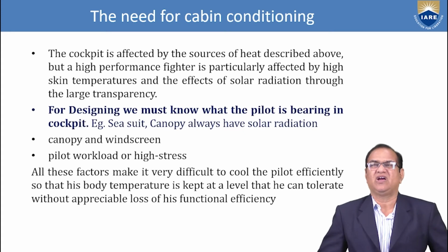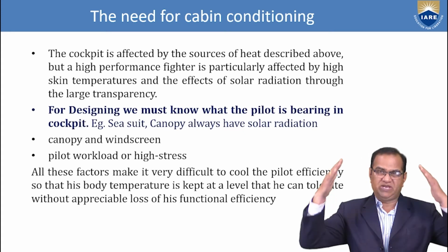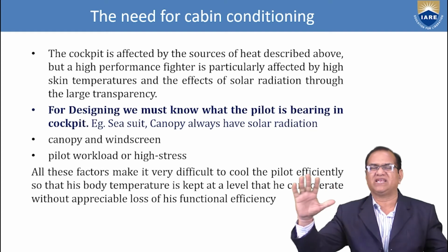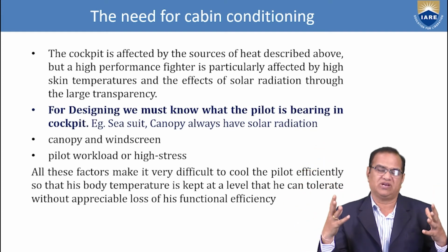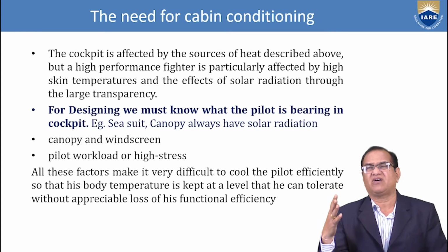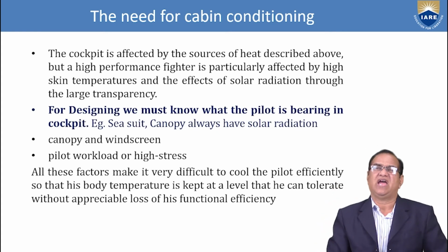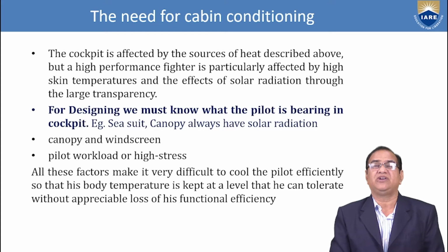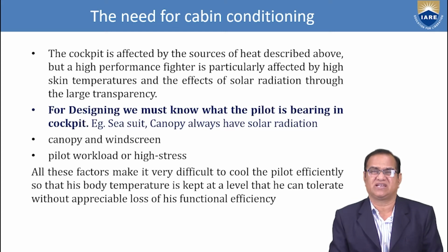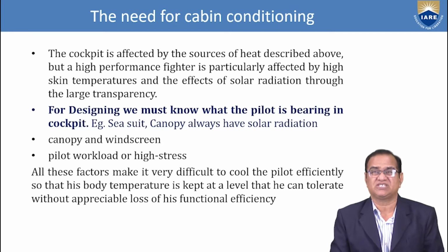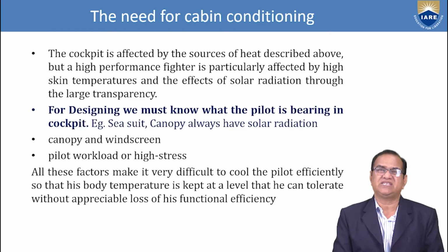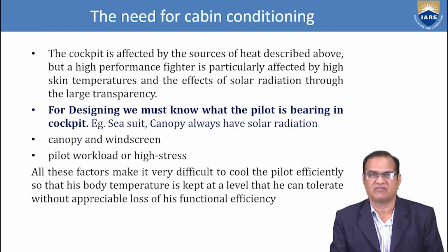If you see fighter aircraft, the canopy on top is full of glass screen and it is flying at very high altitude. So the effect of sun radiation is very high, and also due to high velocity, the skin temperature becomes very high due to shock wave formation. The temperature increases very rapidly, and this is transmitted inside the aircraft.